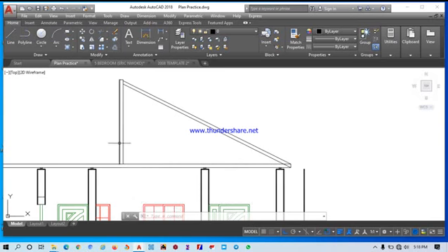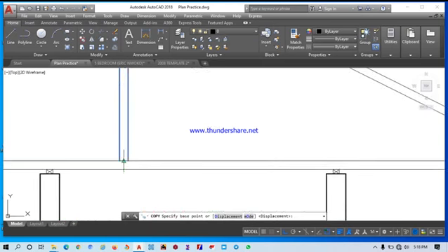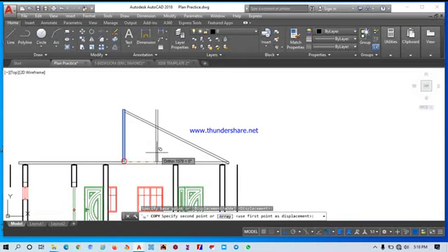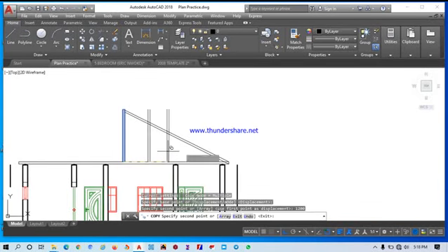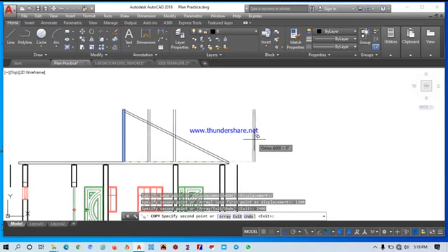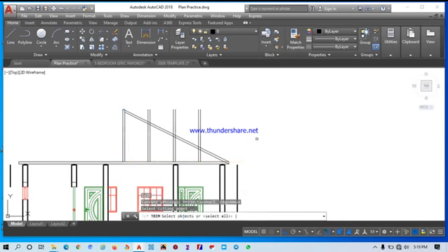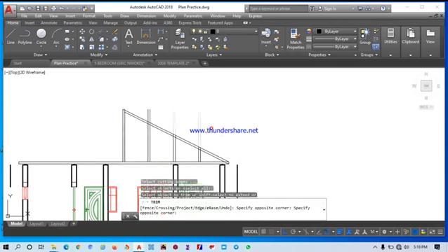Then we have some other vertical members. Some call it queen post, some call it wooden trusses. They have to be spaced at around 1.2 center to center. If you measure the center to center distance, it will be 1.2. So you align those two lines and enter 1.2. If you add another 1.2, that's 2.4. Add another one, that's 3.6. So you just enter that instead of copying them one by one. I think we are good to go. You can trim off this excess.